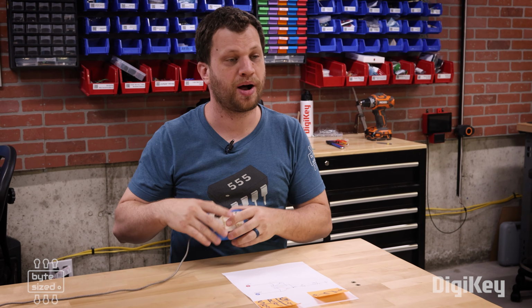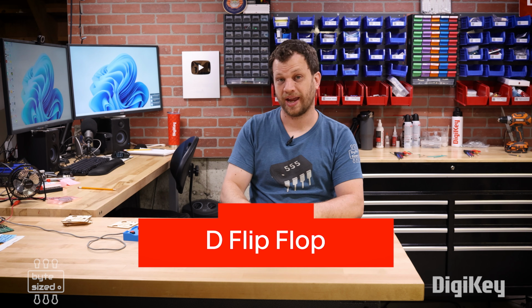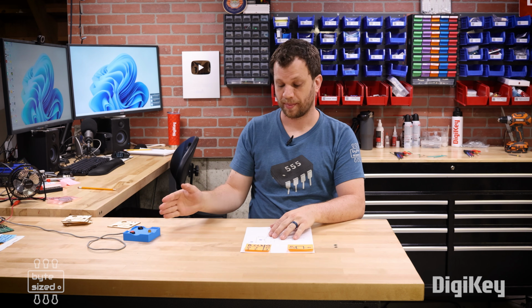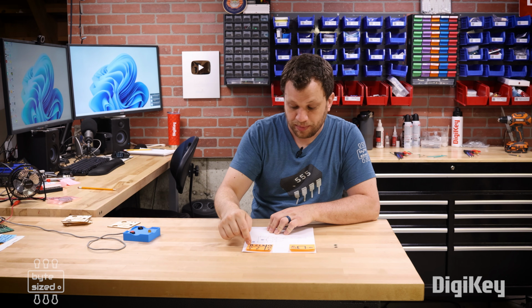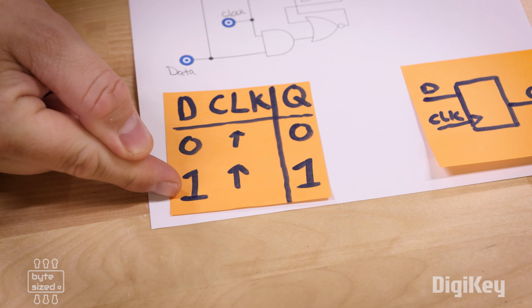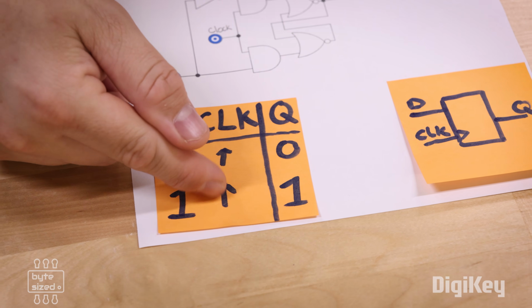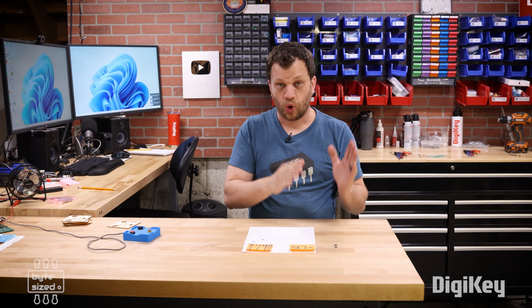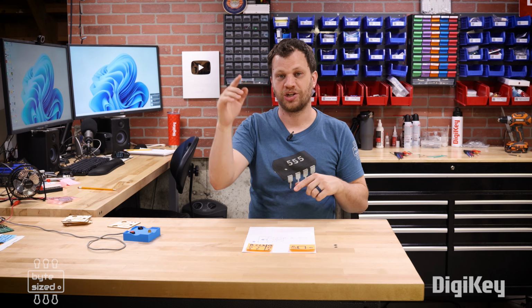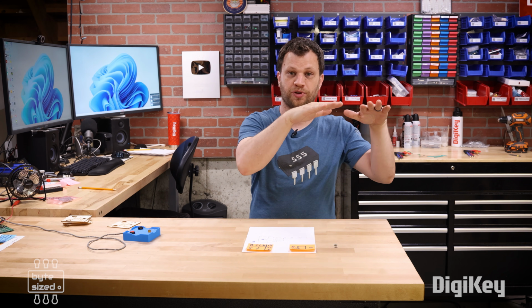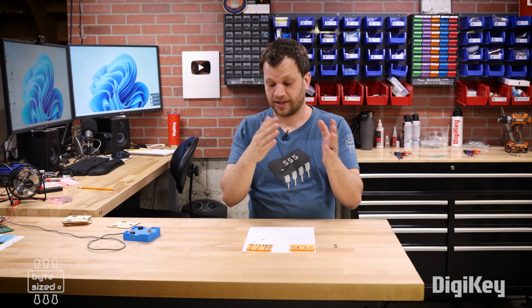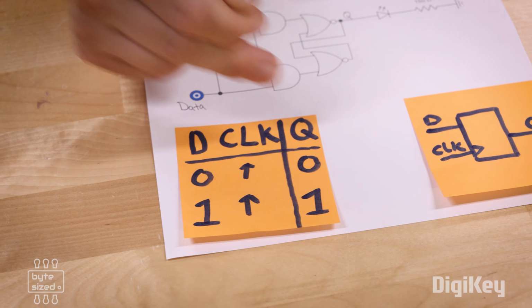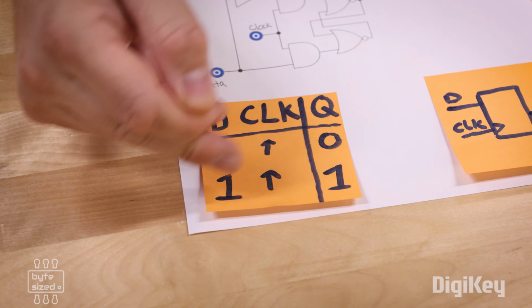So let's fix that problem by creating a D flip-flop. This is a D flip-flop and it improves on the SR flip-flop. So here's our truth table for the D flip-flop. We have our input is D and it can only be a 0 or a 1. And then we have a clock input. And our output only changes on the rising edge of the clock. That means when it changes from a logic low to a logic high, we get that rising edge and the output will change. And our output will match the input on the rising edge.